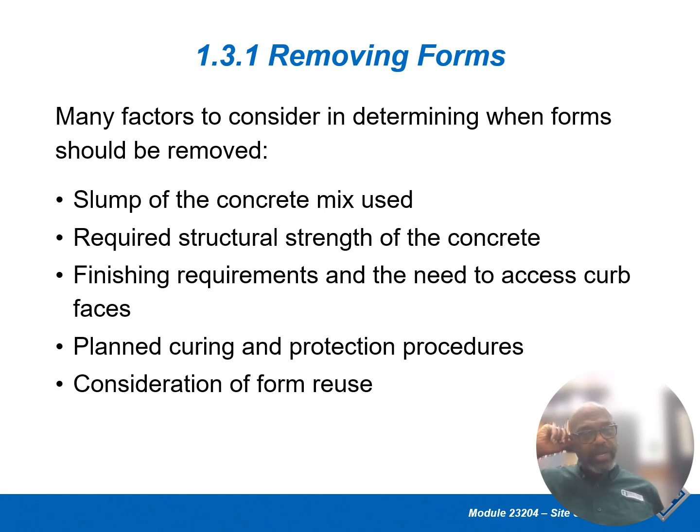So when removing the forms, you have to make sure it's cured. You don't want to remove it too soon, where it can be damaged. Again, you want to make sure that the form has release agent, so you can remove it very easily without damaging the concrete or wasting a lot of time.